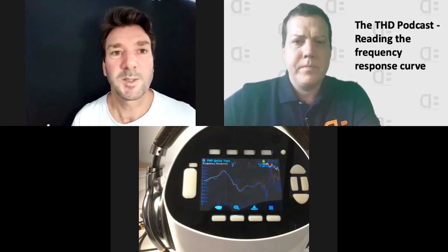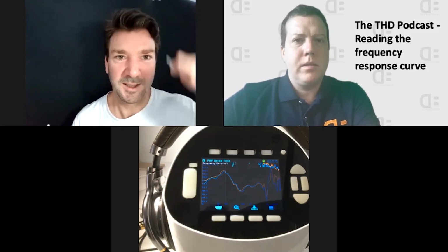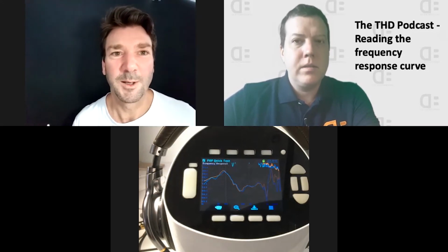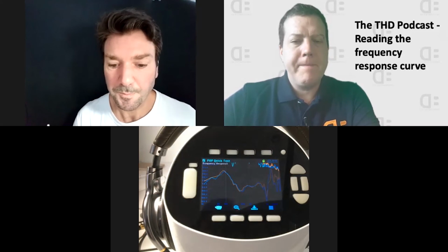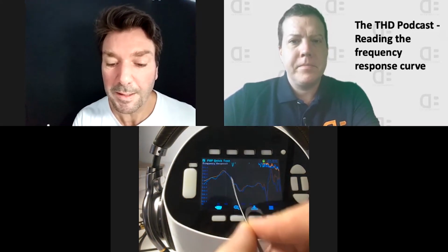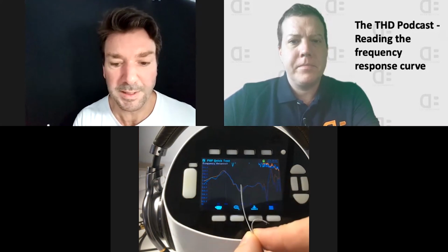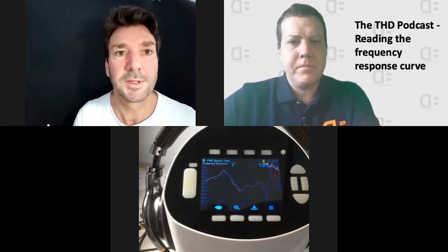So that might be a spec that someone has, like, we like pounding bass, so we want 15 dB or 20 dB gain, and call it gain at the low frequency compared to the mid-range. So it sounds very, very strong. And we'll also say that the bottoming out point is around 200-300 hertz.